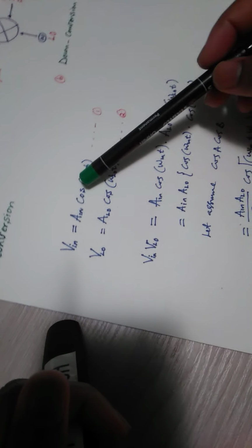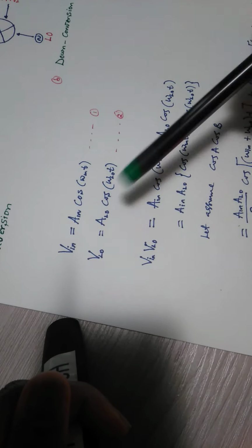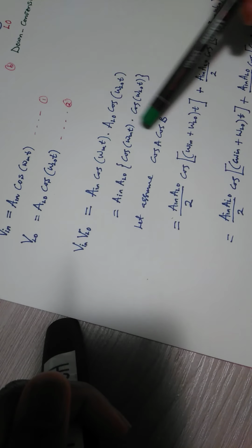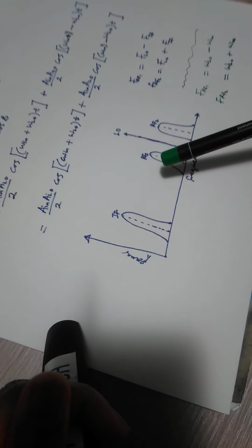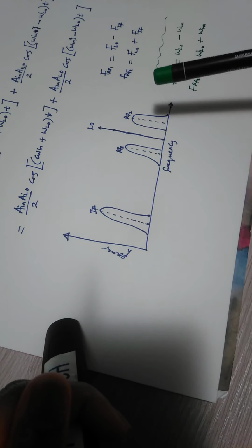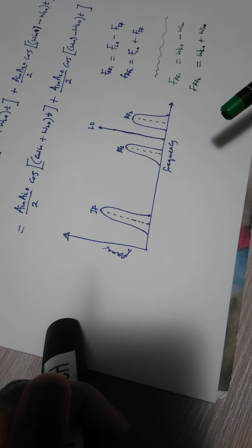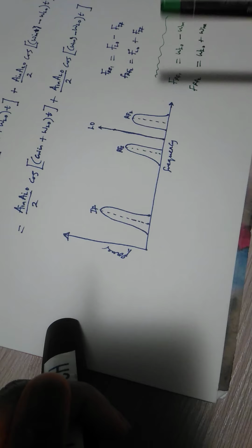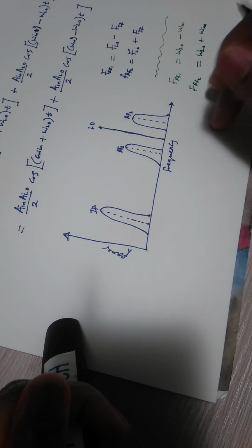And this is the mathematical expression, assuming we have the input signal and the local oscillator combined together, and the picture translation would be what you have explained here. Generally, in common terms, people refer to this as a heterodyne mixer or circuit. This is what is actually happening when you are working with mixers.